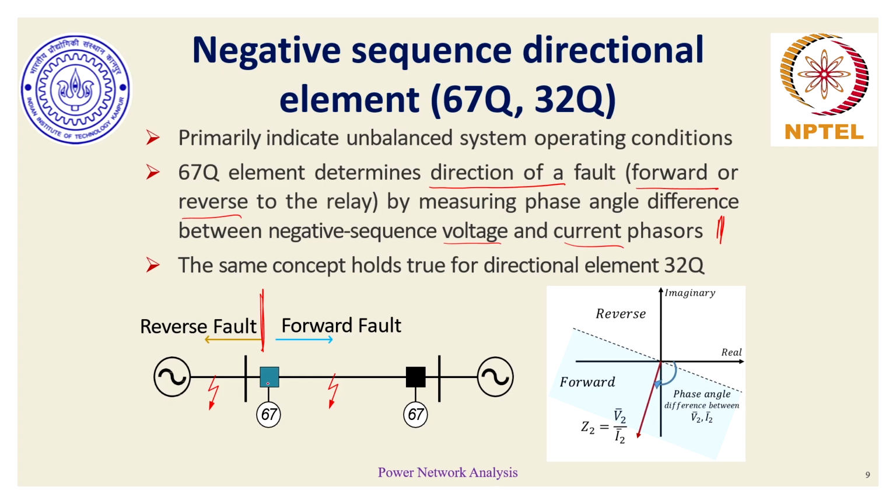Typically the relay present on the transmission line should be operating for forward faults rather than for reverse faults, because for reverse faults there may be another element dedicated to it. So basically that's what we call the reach or set of the relay. So far, with no inverters present, all looks fine from the synchronous generator perspective, because we are able to clearly get an assessment of the negative sequence component present in the network.